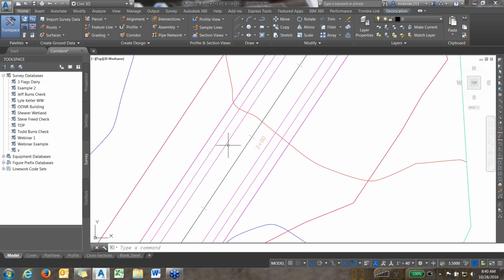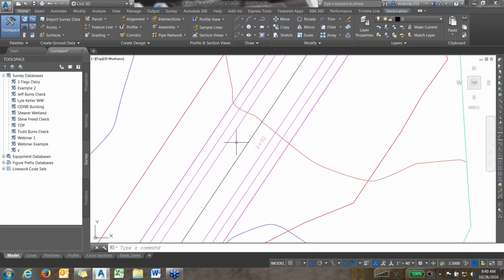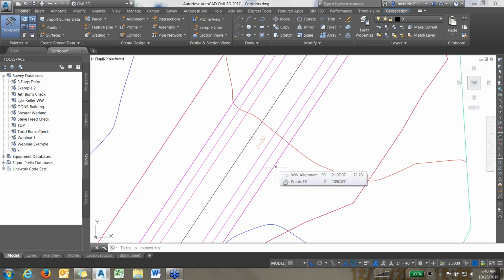Okay, so if you remember how we built the sub-assemblies, we had these different cross-section links all connected together. And then these two outside purple lines right here, those would basically represent the top of my designed waterway. In this case, it was 40 foot wide. So between this purple line on this side to the outside purple line on the other side, that is 40 feet apart. Okay, but then because the profile wasn't properly designed at the right spot, and I did that on purpose, it has to find the existing ground somewhere.